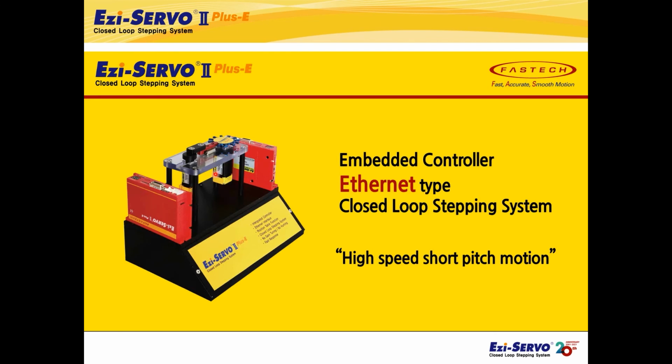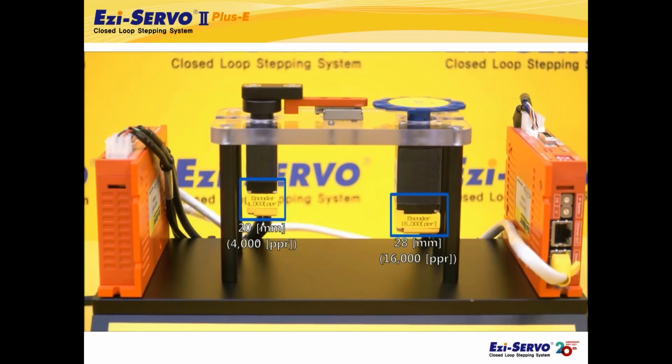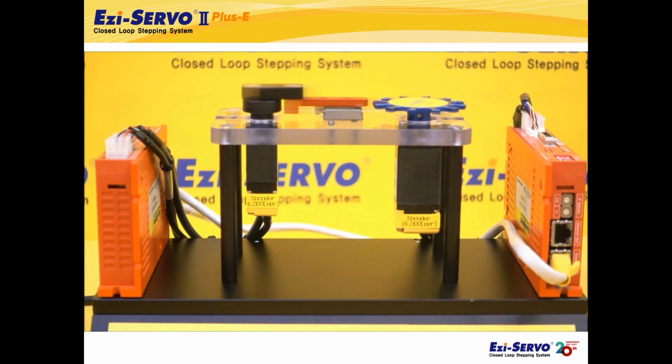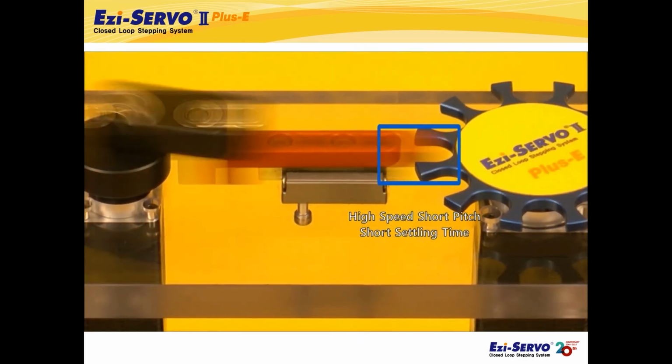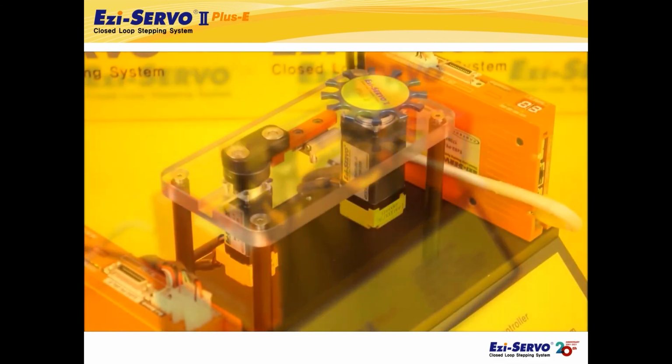This demonstration has a cam-shaped structure mounted on the end of a small stepping motor. It shows high-speed short-pitch motion without collision. The product names used in this demonstration are as follows. Our products provide high resolution of 4000 ppr and 16,000 ppr even with small-sized motors. Due to the characteristic of the stepping motor, it can stop precisely at the command position without hunting even if it moves quickly over a short distance due to its high holding torque.